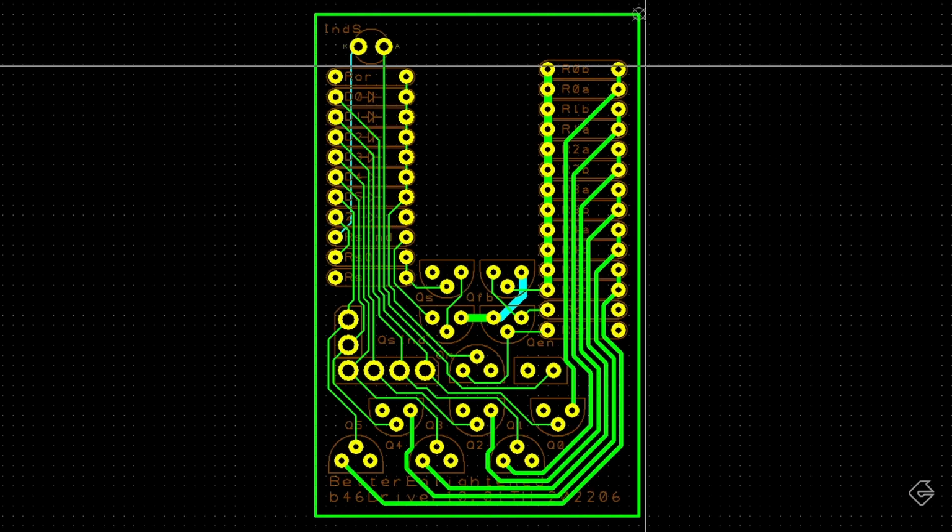And I do not want any trace to be restricting any of the current flow, giving us some stray resistance within our circuit. So in order to prevent that, I tried to make them as fat as I possibly could while still keeping the size of this board fairly small. The other thing you'll notice is that there's a whole lot more resistors here than there is in the circuit diagram. And I also did this deliberately.